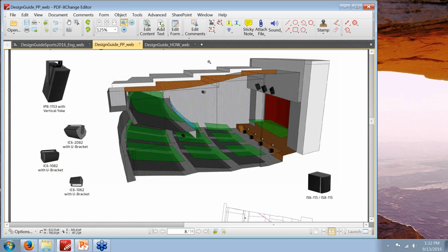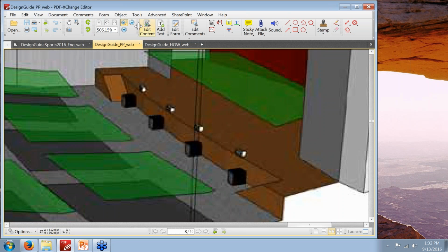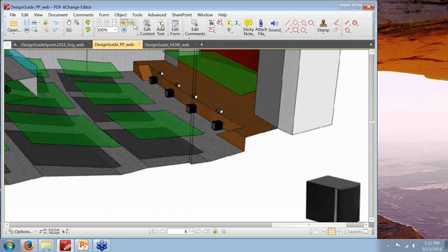Generally, the spacing here, here's one of those designer tips, the spacing between these locations should be no bigger than the wavelength of your low-pass filter. So if your subwoofer is, for example, passing at 80 hertz down to 30 or 40 hertz, whatever its range is, you wouldn't want to space them any more than that.